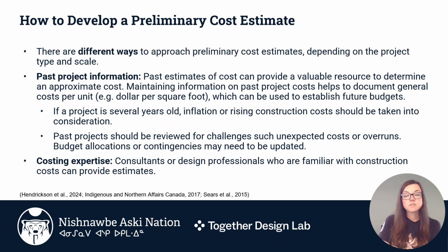Now, if we wanted to build a 5-bedroom house that is now 2,200 square feet, we could use that same dollar per square foot value multiplied by... $282 per square foot times, say, 2,500 square feet, it will be around $700,000. This is a very basic way to calculate this information, but sometimes that's the best way to do things if you have the total cost of past projects.